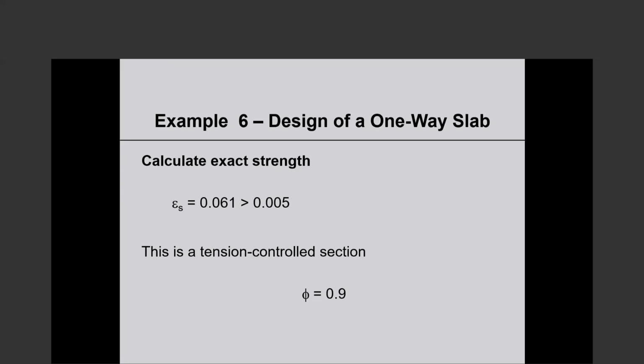Okay, go ahead. I'm just trying to rephrase the question. So, if on one side of a beam there is a column and on the other side there is a shear wall, what should be the span? So the beam is bearing on a shear wall. That's fine. If the beam is bearing on a shear wall, it is no different from a beam bearing on a column. I don't know, because the shear wall is stiff. You think the span should be changed?